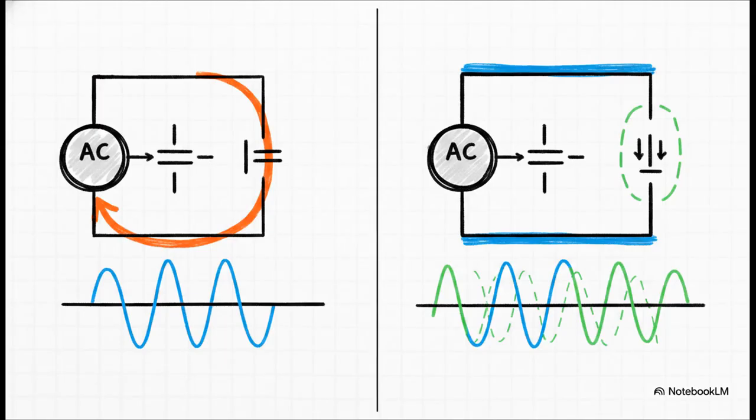To wrap up our comparative journey today, let's really lock in these fundamental takeaways for AC circuits. When you place components in a series circuit, they all share the exact same current. Therefore, we use the current as our baseline reference to mathematically align all those shifted voltage waves. But when you place components in parallel, they all share the exact same source voltage. So we use the voltage as our reference point, and it's the individual current waves that shift around. The golden rule here is to always look at what the components share to ground your perspective.